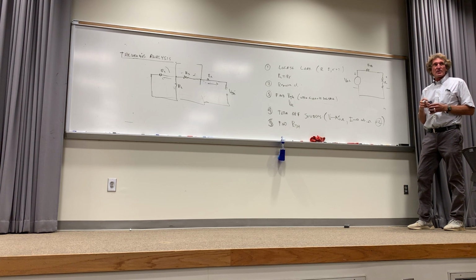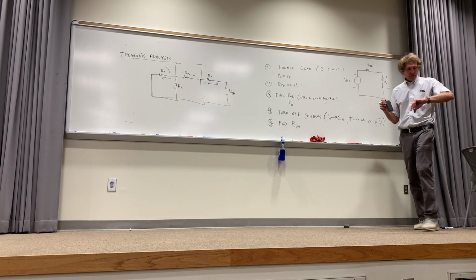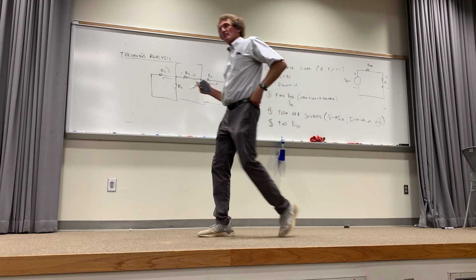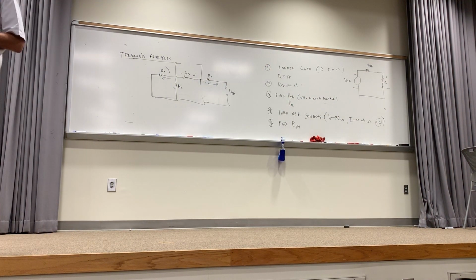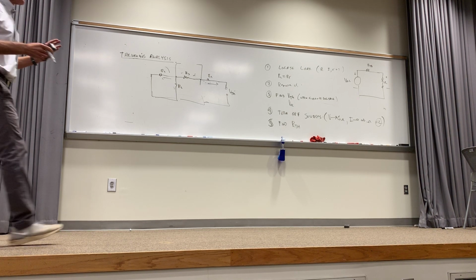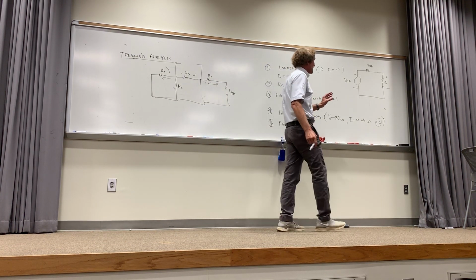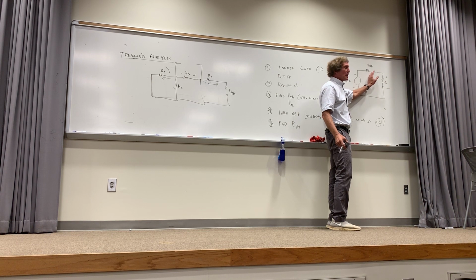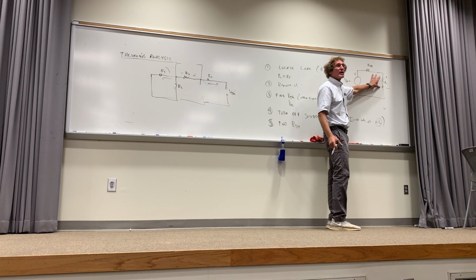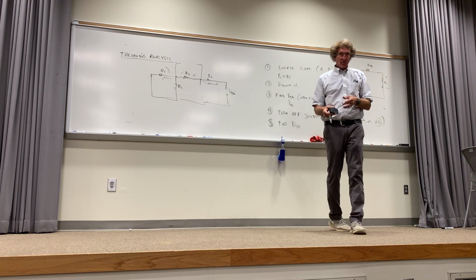Okay? Now the way I'm going to get this through to you is do problems. That's where you'll see this. And I'm going to hopefully get 3 into it today. All right, now this is, what I'm doing here, this is a very, very powerful technique, and here's why. Because a lot of times, you might have 10 different loads that you're going to attach to the output of some circuit. Well, if you want to, you can analyze the circuit with all the elements with that load. But if it's a linear circuit, then you have only 2 elements here, and when you can start changing the resistance value, very quickly see what happens. You follow me? And you don't have to do that large-scale analysis every time. Are you with me on this class?